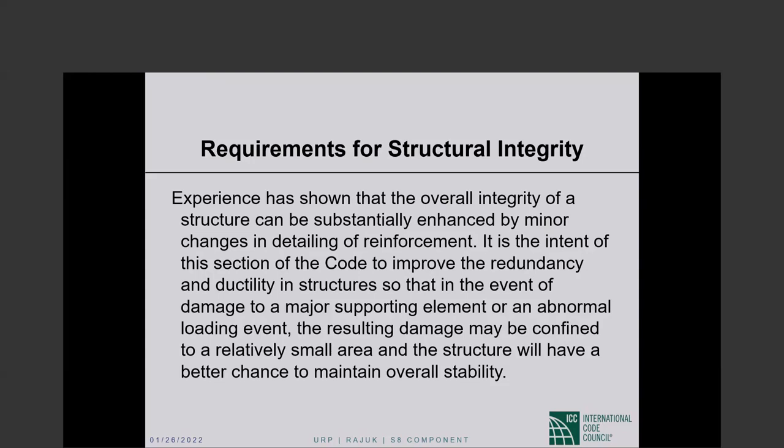But the further away you go from the tension face with these layers, the less effective your reinforcement becomes, right? Tension reinforcement is the most effective when it is close to the tension face. So it will be in your interest to keep the layers as close as possible, not violating that 1 inch gap. So there is no upper limit because who would think of putting an upper limit? It is in your interest to keep the layers as close as possible to the tension face.